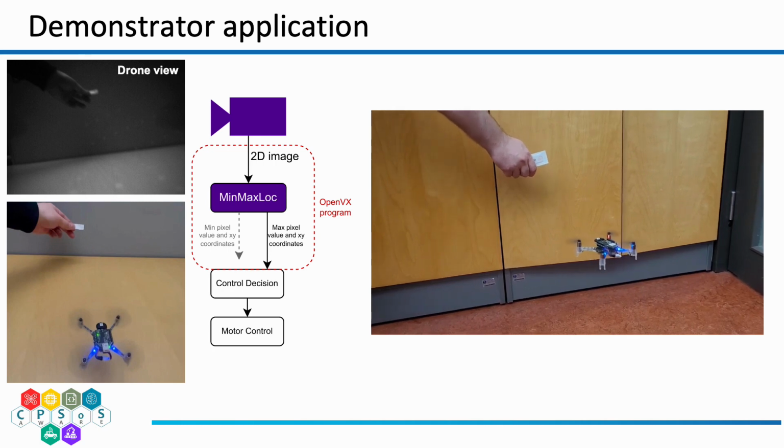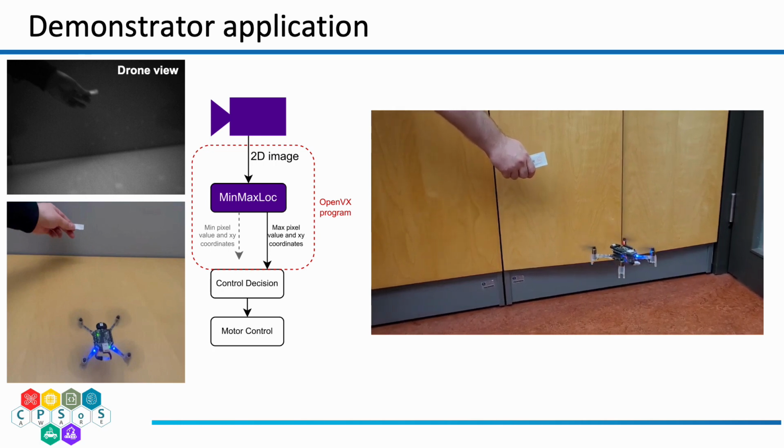The lag in the control reaction stems mainly from the slow transfer of the image. One of the bottlenecks is moving the uncompressed image through the AI deck's slow onboard connections from the RISC-V chip to the Wi-Fi chip. The Wi-Fi connectivity between the drone and the router was also found to be unreliable, which caused additional lag due to retransmissions of network packets. Optimizing the data transfers is found to be the most critical next step for efficient remote offloading.